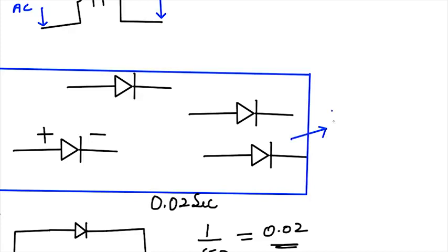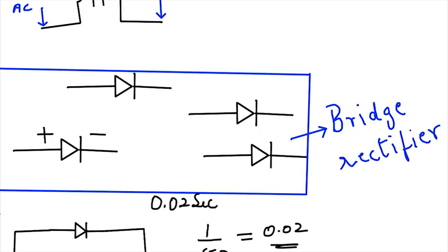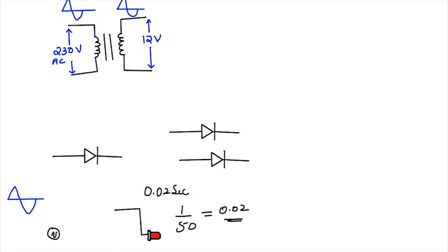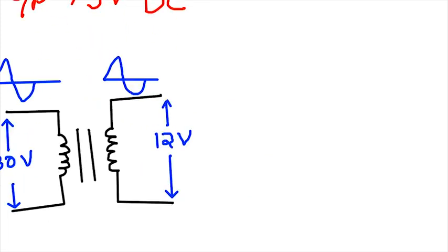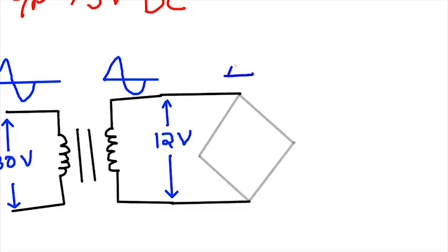I guess for few this may ring a bell. A combination of 4 diodes is mostly used in a bridge rectifier. Now the question is, how do I combine it to form a bridge rectifier? Well, that's easy. We just need to draw a square box like this and mark the terminals on its 4 corners. Let the top and the bottom be for the AC source. In the right, let's have the positive terminal, and in the left, negative.